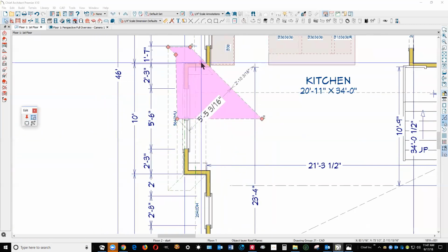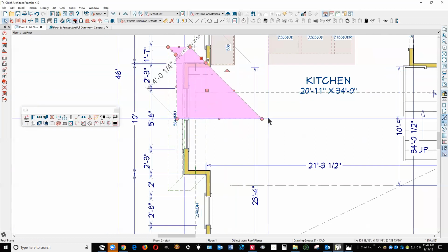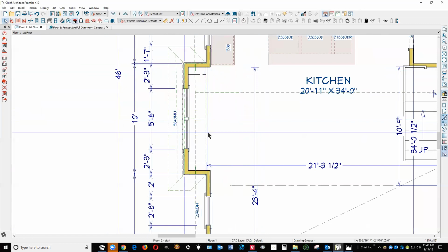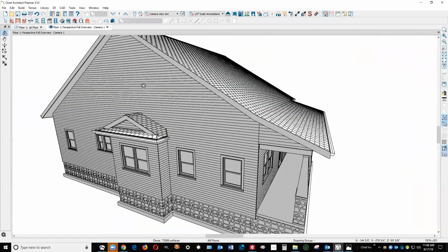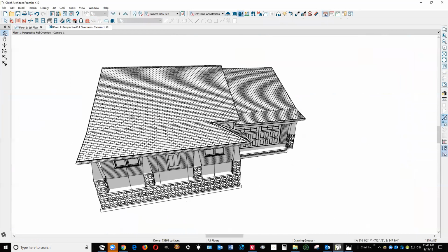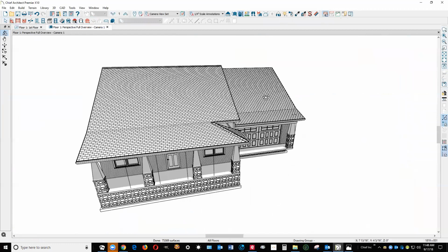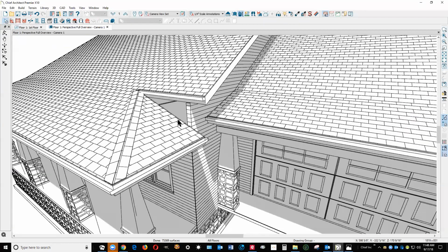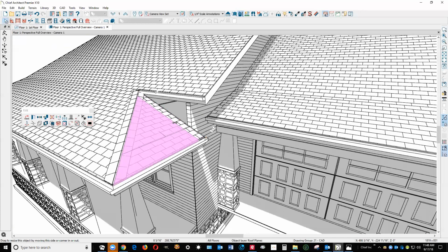Again, I'm just reshaping the roof polylines into a different configuration so that we get a nice flat wall there. That's probably something like that is there. Who knows? I haven't seen it, but that's better than it was. Now we need this gable here, which is what you asked me to help you with. But I had to kind of set things up first. And we got a little bit of a situation here. We need to probably pull it back a little bit so it's not stopping that wall to build.